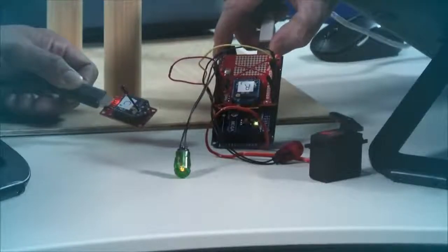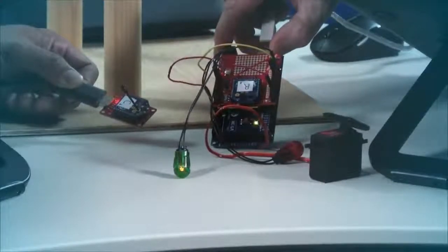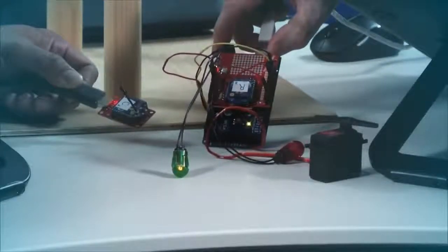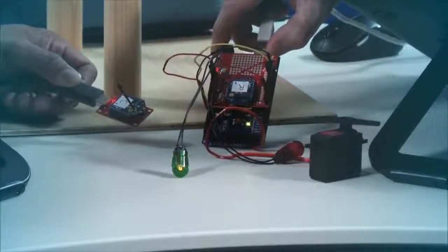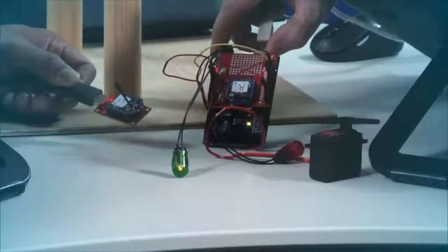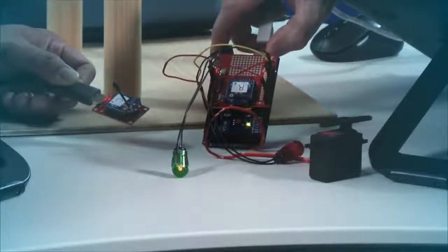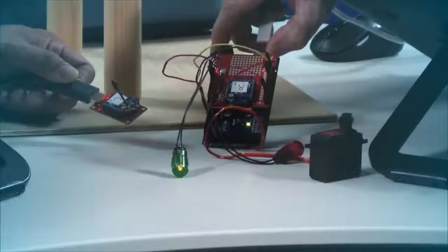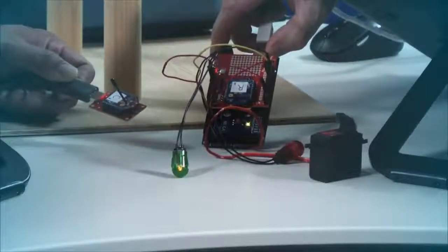But you can see the shield that was purchased for it has this little tiny switch on there because it's using serial in the same way that the Arduino board uses serial. Having a little switch that allows you to program the board without interfering with your serial RF communication is a nice little switch, right? Otherwise, you'd have to take the RF module off of the board while you're sending the program to the Arduino board.